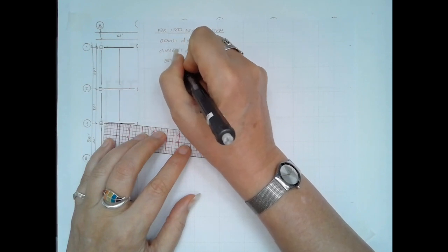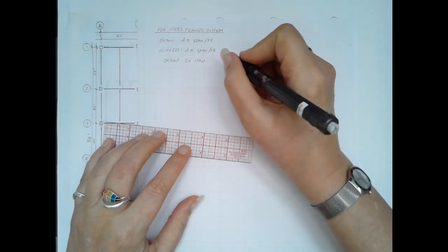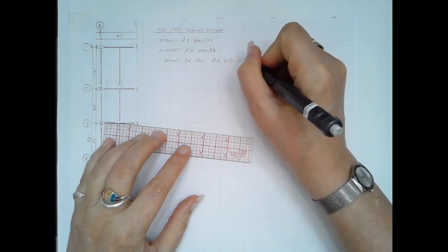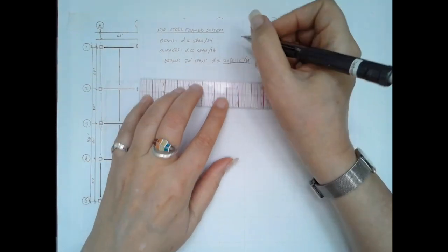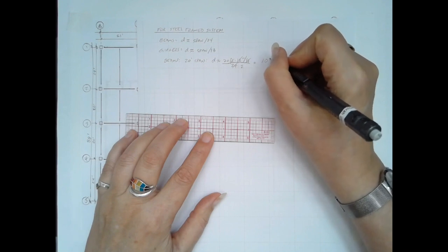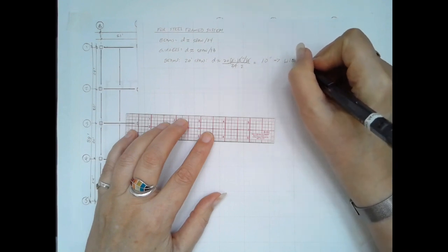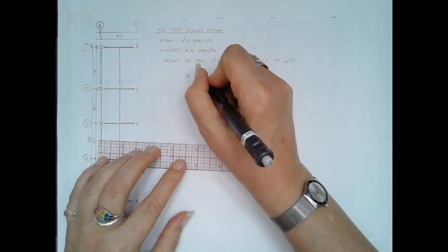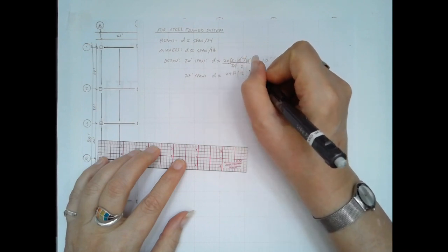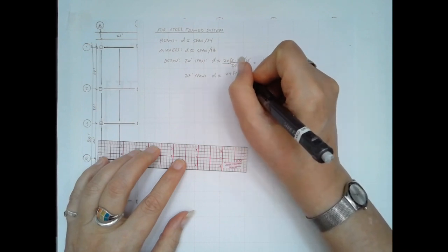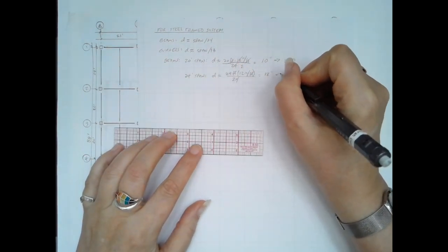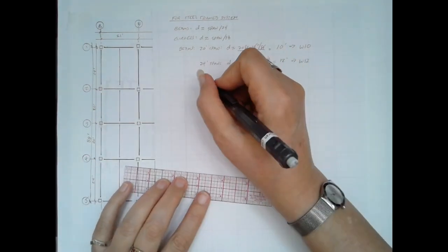So first we look at the beams. We really only have two beams. One is a 20-foot span. That's between lines 1 and 2, or excuse me, 2 and 3, and also 3 and 4. So that gives me an approximate depth of 10 inches, so we'll select a W10 member there. Now we don't know the size of that member until we actually do load calculations, but this gets us in the ballpark. That's the objective here. For 24-foot span, span over 24 gives us a 12-inch beam, so we'll have W12s there.